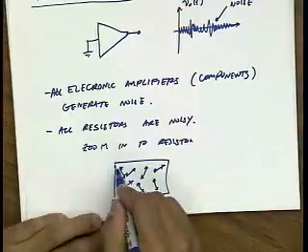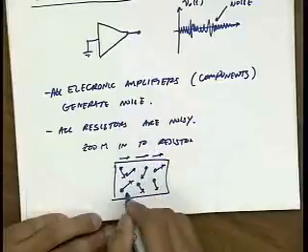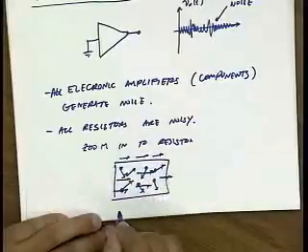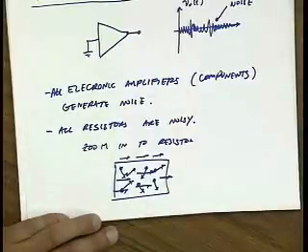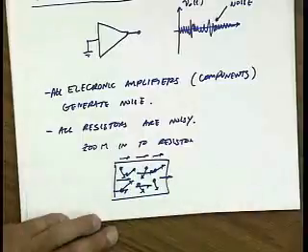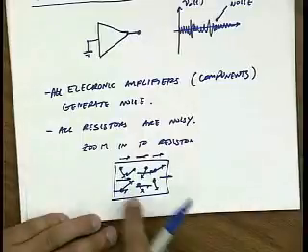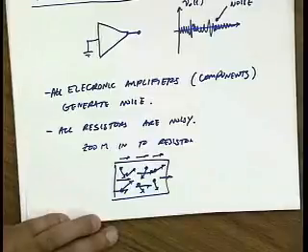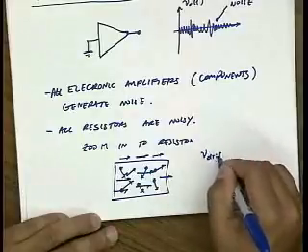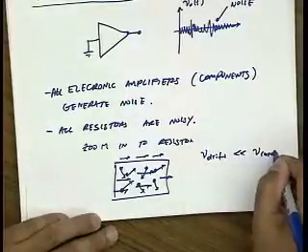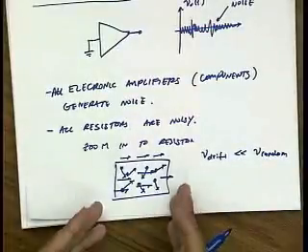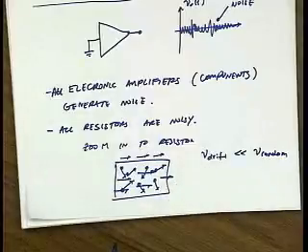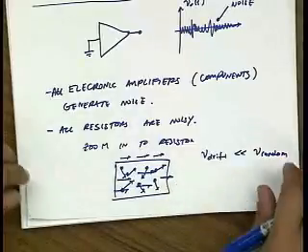And when we apply an electric field, we get a drift, a small motion that's proportional to the electric field, but the electrons still continue to move about seemingly randomly. In fact, it's hard to even see them moving in the drift direction at all, because the drift velocity is usually much smaller than the random velocity. Because they're moving about randomly, the potential across this resistor also varies randomly, and you can study the statistics of that process in detail.